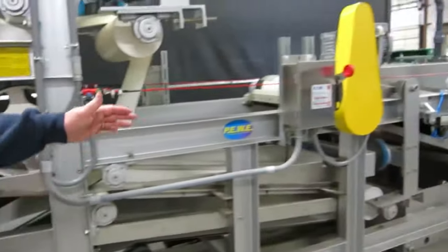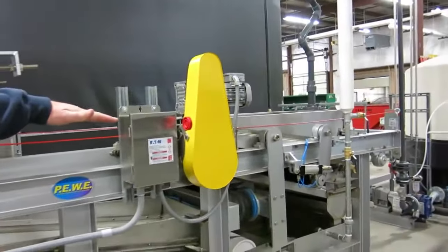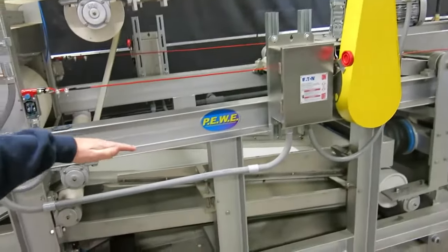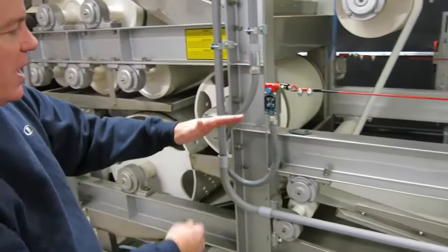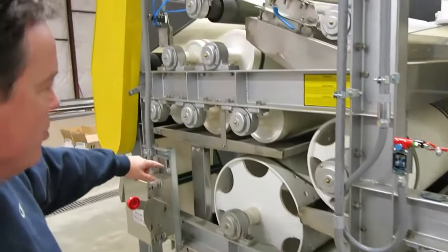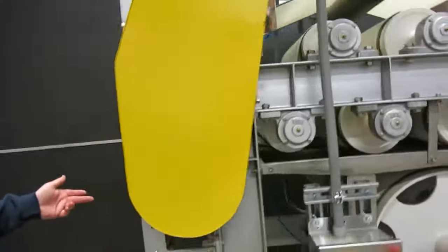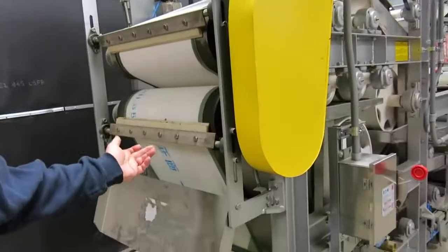The way the system operates is we first gravity dewater the solids as they hit the belt. They fall onto the main belts. They're squeezed in a dual action pincher motion, go through the press itself, and then fall off the press at the doctor blades.